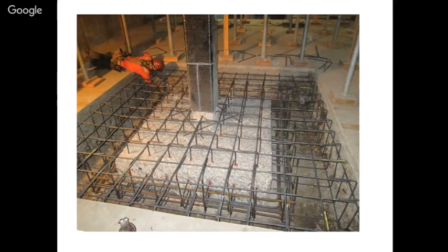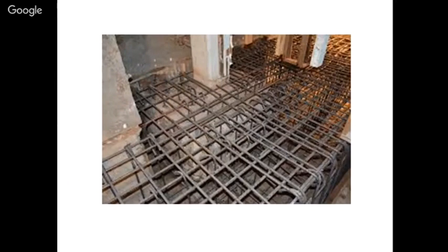You can see the existing foundation level has been increased. Then increasing the foundation capacity, because they have already strengthened the column using FRP. Now the strength of the column is very, very large as compared with the foundation. So you can see, if you have multiple columns, you can go for a joint foundation during retrofitting.